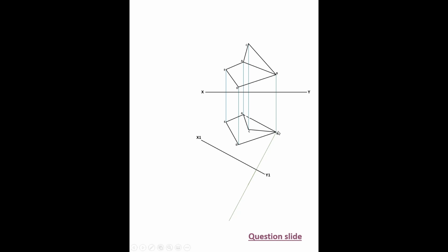So how we find the points on our new auxiliary line is we use a method called the 1-2 rule, or 2 views back, as I like to say. That's a rule that has to be taught, because you always have to go 2 views back in order to find your lengths for your points on the auxiliary. So we bring down all our points first of all, A, B, C, D, E, and these points are perpendicular to the x1 y1 line always. So we extend all these lines out first of all.